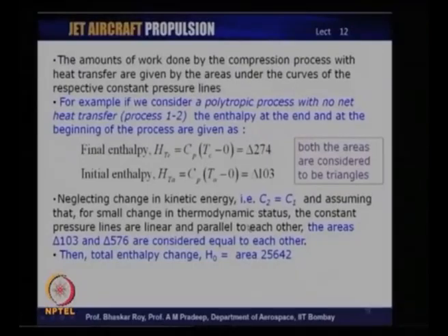So, this is what we learn from simple thermodynamic analysis: you can use thermodynamics as a matrix to figure out what is going on in the compression process, and then see whether you can get your compression process done a little more efficiently, a little more effectively, so that it serves the purpose of the jet engine and brings the jet engine closer to the ideal Brayton cycle, which is the matrix on which the jet engine is functioning.